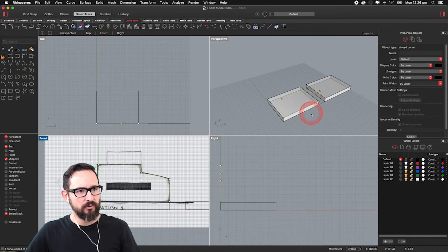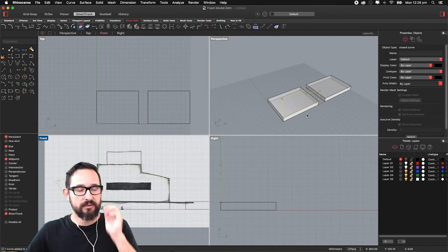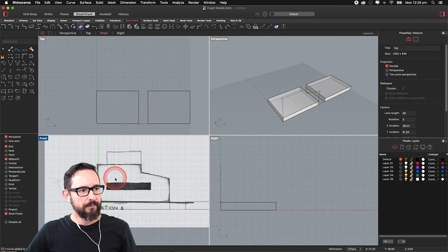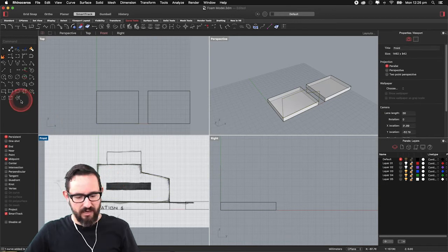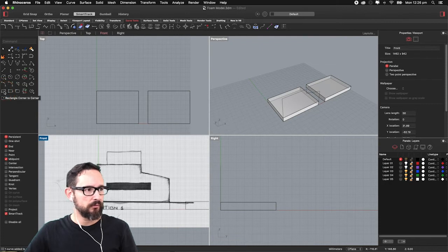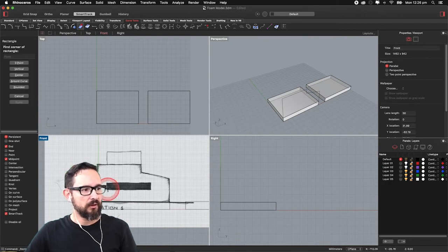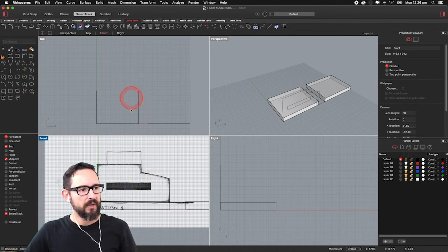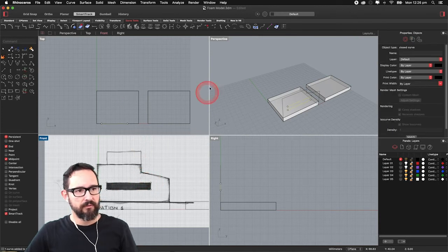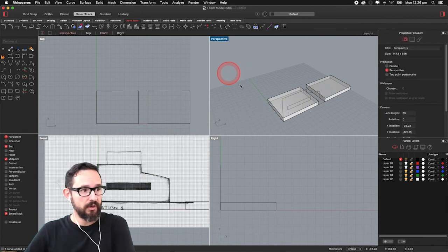As you can see, we drew it there, which is convenient because now we can actually also draw this rectangle. In this case, I'm immediately going to get the rectangle in because I don't want to draw a polyline. I'll just click on the rectangle or write the command rectangle and just trace it, right? But again, if you know the dimensions, that will be the correct way to do it.